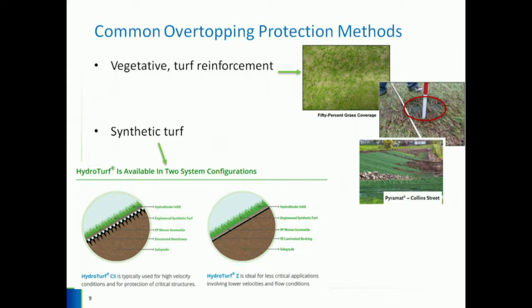where the material underneath eroded, so you can see the turf reinforcement actually displaced downwards. Here you can also see the turf reinforcement over which they're laying down soil. You can also have synthetic turf. This is not natural grass, and it's placed over a layer of geomembranes. You can see here, and this is a subgrade material, a geomembrane over it, and then you have a geotextile over the membrane, and finally the turf material with an infill. So you can see two different types of geomembrane, and we'll talk about it when we come to that type.